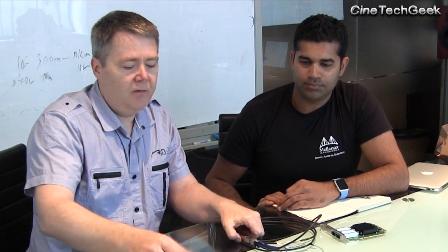So for these ultra fast networks, the faster you can go, the better, right? But you also need to look at these pictures. You need to put them on grade 1 monitors or projectors. How do you get to these projectors and monitors? Well, that's when you all of a sudden have to also implement in your facility coaxial infrastructure for sending SDI over coax around. Once we have a converter which goes from network to SDI, that need has disappeared. You only have the one infrastructure, and that's all Cat6 or fiber.